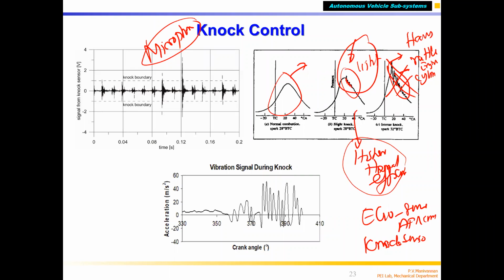If you accelerate, you will see that the engine will make a lot of noise and jerky movement, and the vehicle will stop. If you are a new learner of any vehicle, whether two-wheeler or four-wheeler, you will notice that. So what happens is, if you apply brake, vehicle speed will come down. Your gear is in fourth gear. In fourth gear, the engine doesn't produce sufficient torque because you have removed the throttle also. Because you apply brake, you reduce the throttle also.